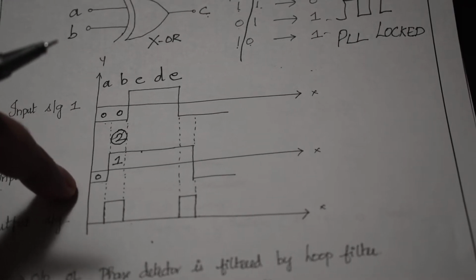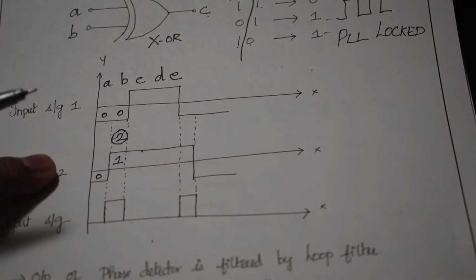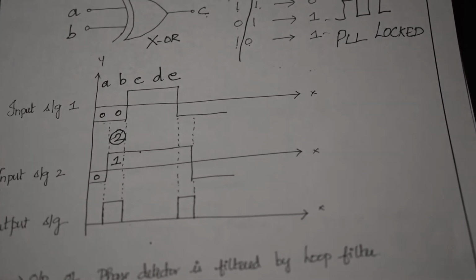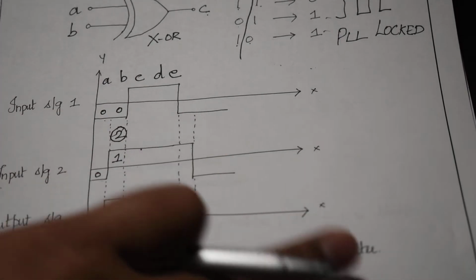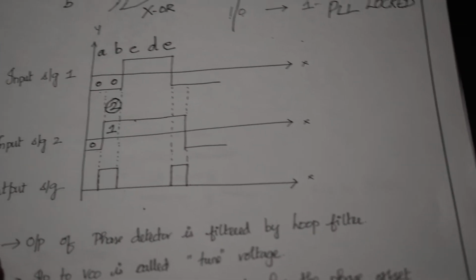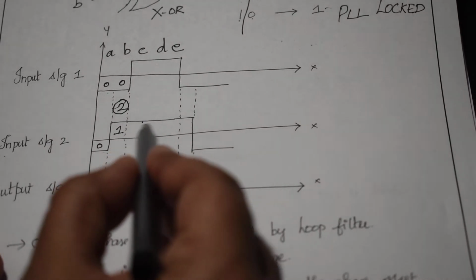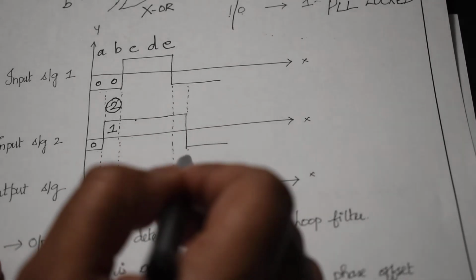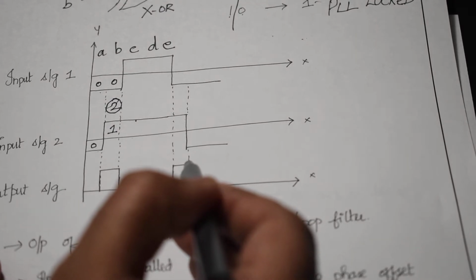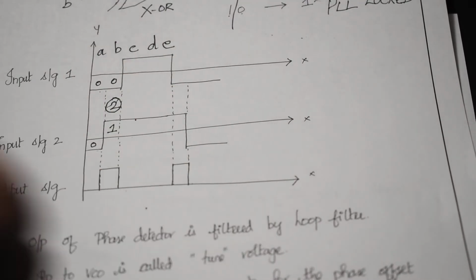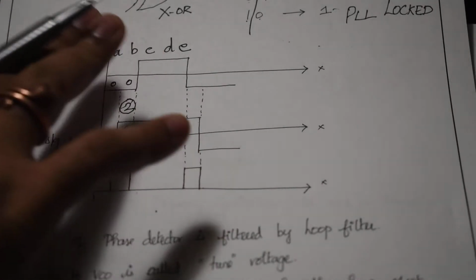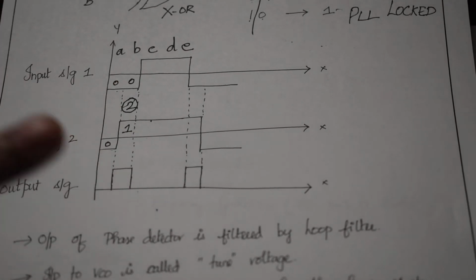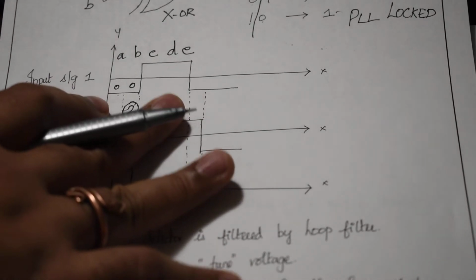You can very easily realize this on a basic PLL circuit with the basic breadboard and two signal generators and an oscilloscope or a signal analyzer. And whenever there is a difference in the phase, which is either it is high or low, you generate a signal that is proportional to the difference of that. So this XOR is a basic understanding for the function of the phase detector, but it is not exactly an XOR. This is just for the understanding purpose,